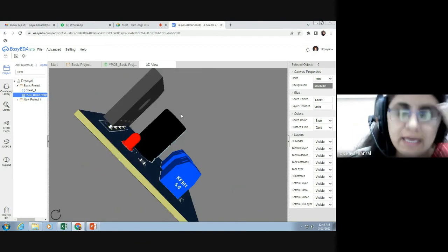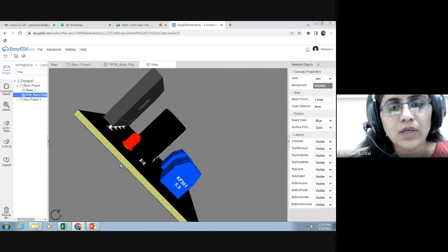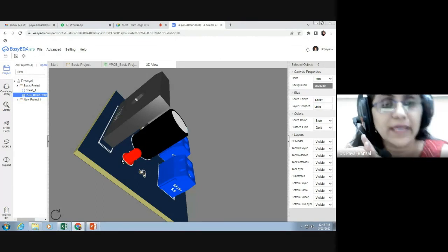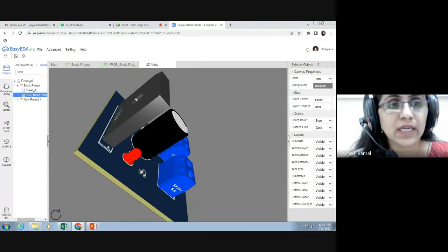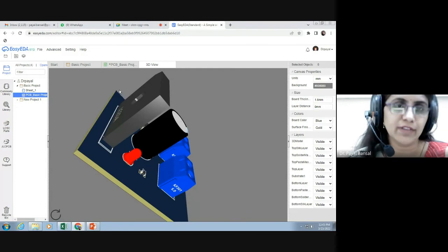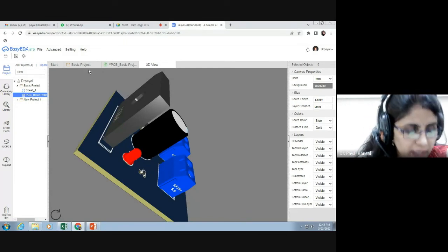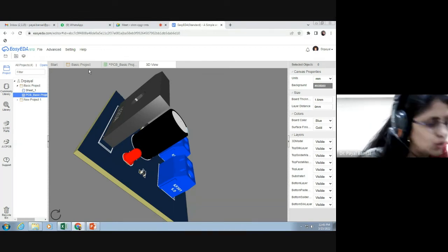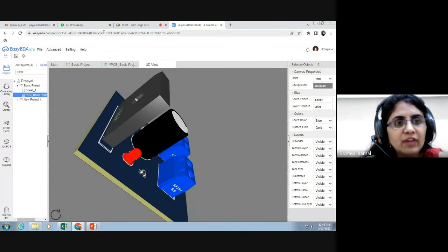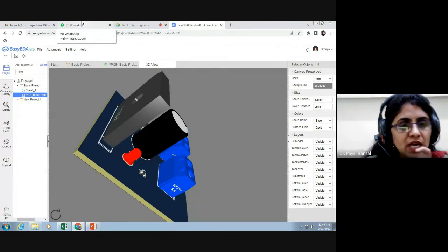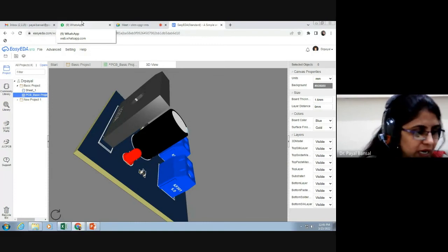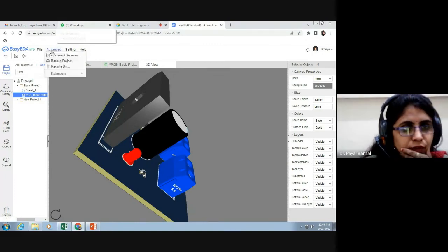Now the final step is, if my design is final from all aspects, all criteria, it is perfectly okay, then I just want to make it as hardware. What I have to do to make it as hardware, I just want to make its Gerber file. Gerber file is the type of file which I should send to the hardware designer to make it as hardware. Fine. For that purpose, we have to click in that file,